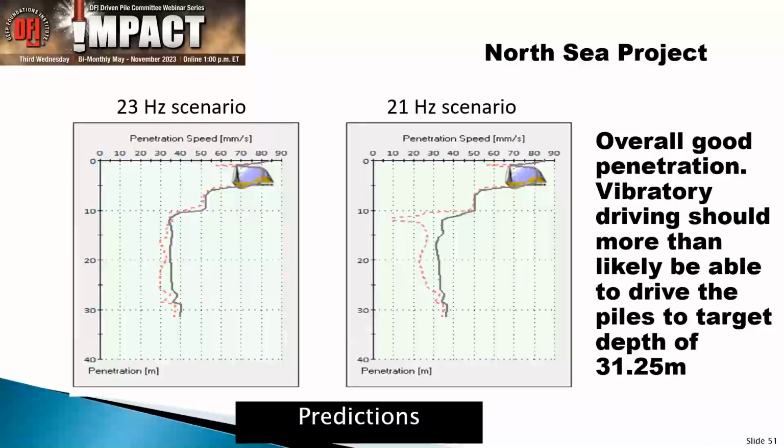The weights that I showed you here in these examples of the piles and offshore piles are generally way higher. So if we're a little bit off on the weight of the clamp or the weight of the hammer, it's not that big a deal. Plus, quite often, with an offshore project, you have a number of hammers working in parallel, which means I have to have a very stiff plate underneath to make sure that the action is really shared or spread over the whole pile. That very stiff plate is generally heavy. So from that point of view, it's not that important.